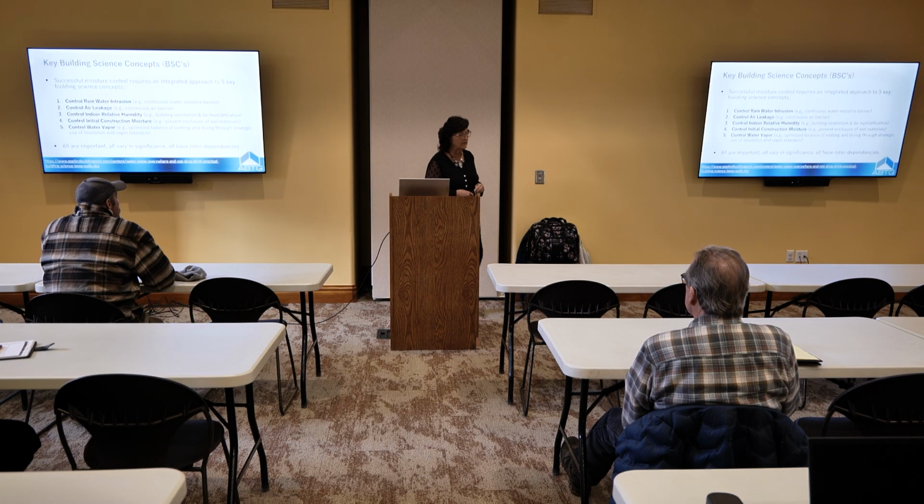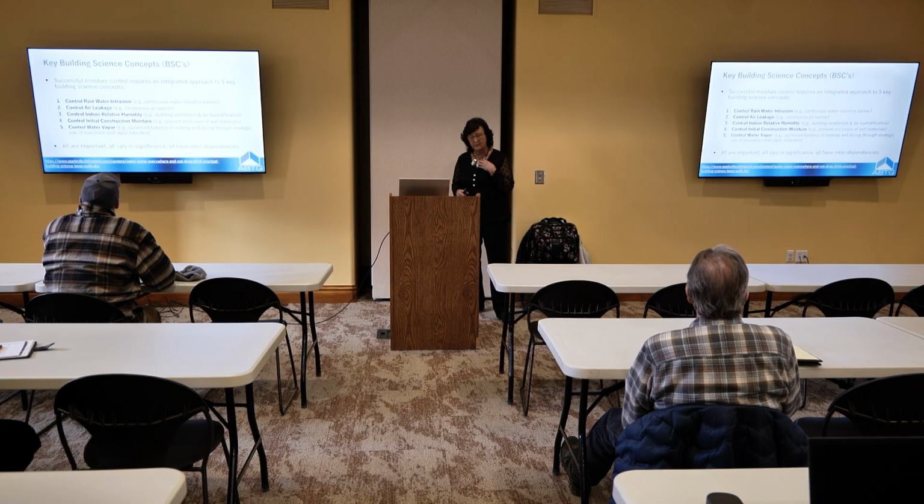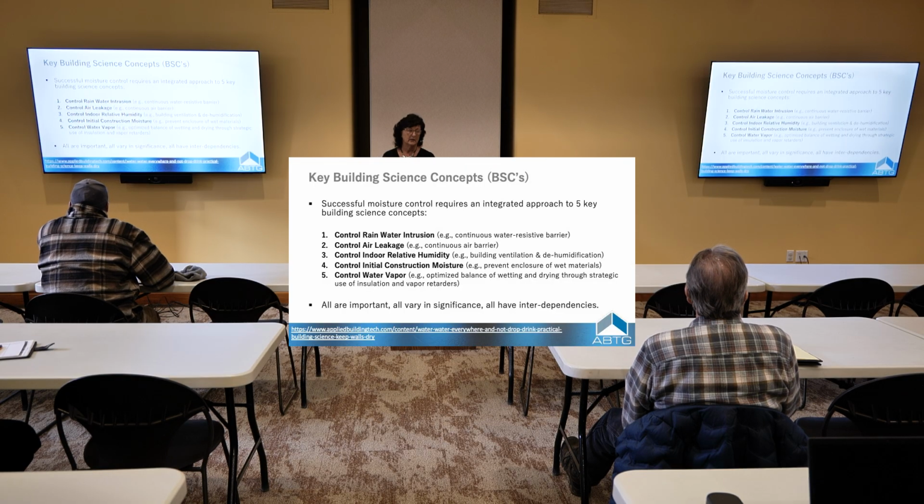There's a lot of ways to do it. There's a lot of ways we get moisture in the building: just water intrusion because we didn't seal it up, or we didn't protect our products. Air leakage, wherever air can move, so can moisture, right? Again, not sealing it up, not having a continuous air barrier.